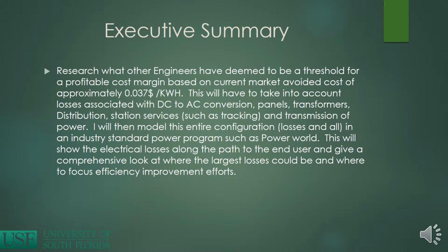This will have to take into account losses associated with DC to AC conversion, panels, transformers, distribution, station services such as tracking, and transmission of the power. I will then model this entire configuration of losses in an industry standard power program such as PowerWorld. This will show the electrical losses along the path to the end user and give a comprehensive look at where the largest losses could be and where to focus efficiency improvement efforts in the future.